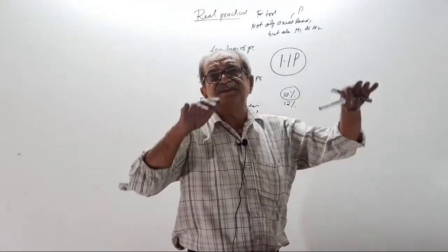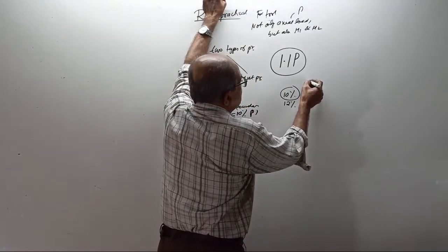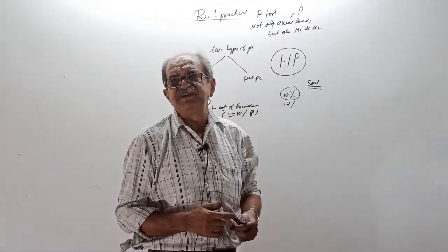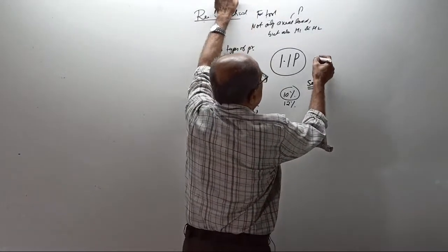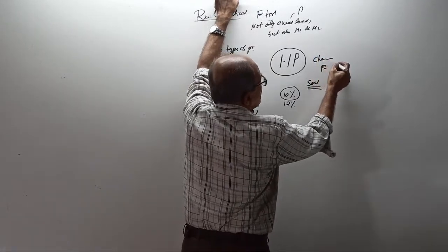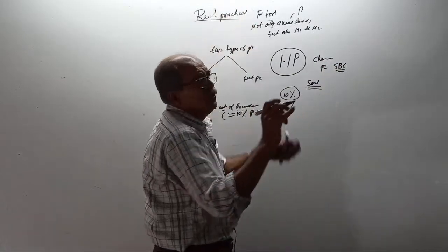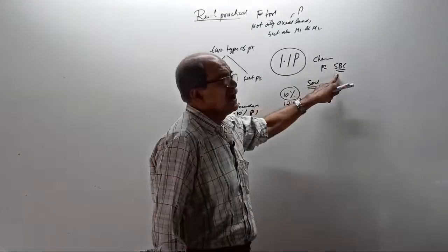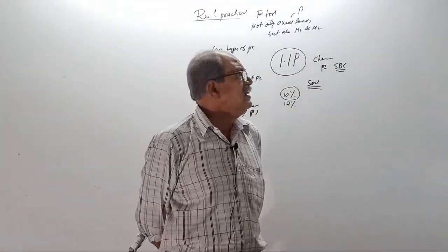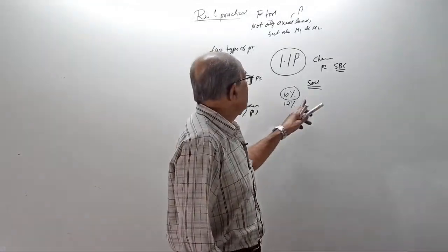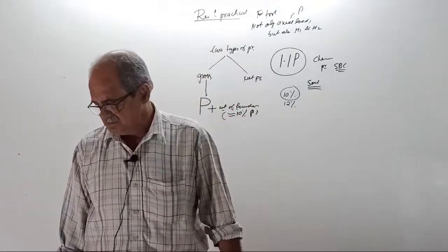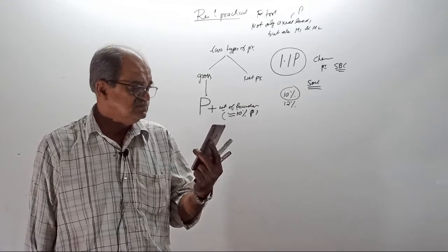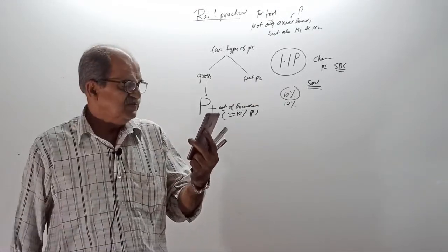When you consider the safety of the soil, tell me, is gross pressure required or net pressure? For checking the pressure against the SBC, we do not want the pressure on soil to go beyond SBC. When you want to ensure that it is not beyond SBC, shall we consider gross pressure or net pressure? This also I told you, you forgot.